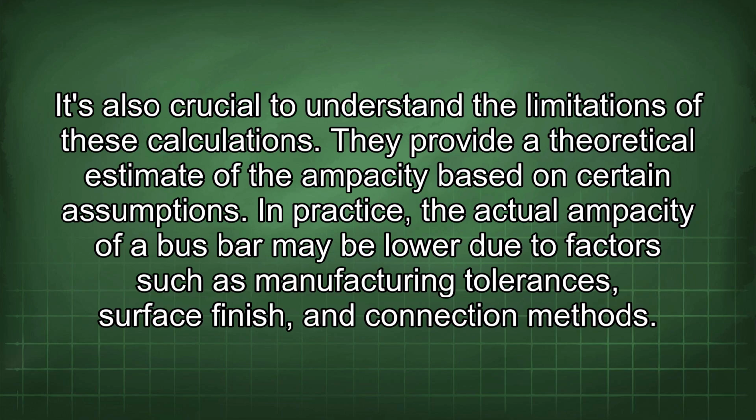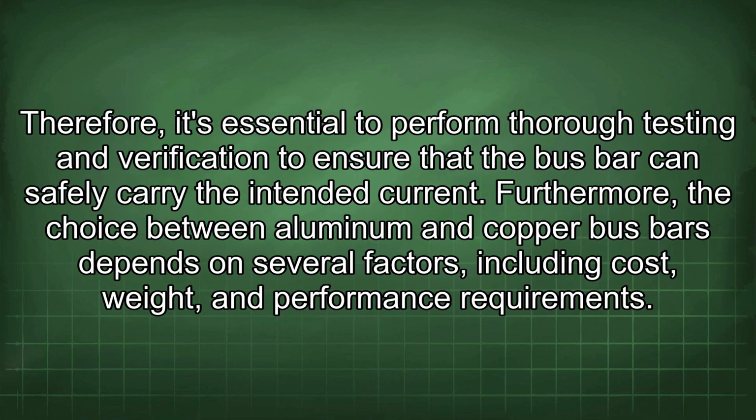It's also crucial to understand the limitations of these calculations. They provide a theoretical estimate of the ampacity based on certain assumptions. In practice, the actual ampacity of a bus bar may be lower due to factors such as manufacturing tolerances, surface finish, and connection methods. Therefore, it's essential to perform thorough testing and verification to ensure that the bus bar can safely carry the intended current.